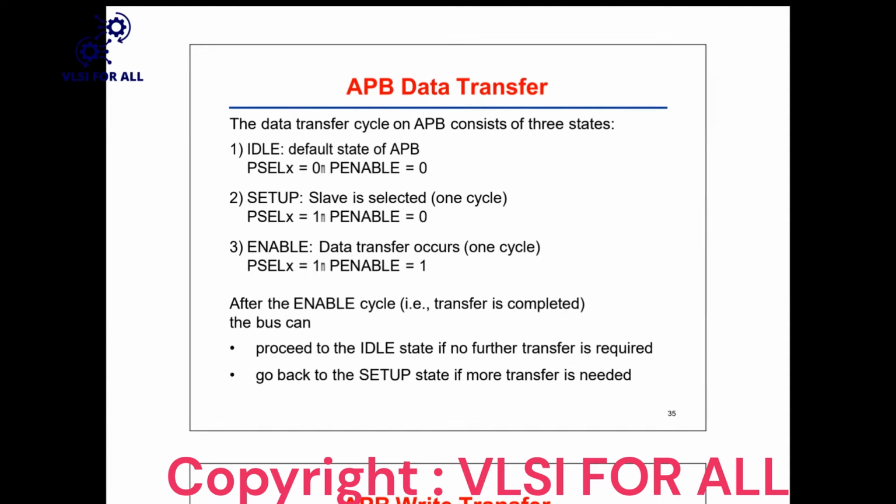But when a transaction has to be done, it has to come to the setup state. In the setup state, PSEL will be high, which means the slave has been selected, that is, the slave with which the master has to communicate. But data is not yet driven, because the slave is just selected from the master side, and whether that slave is ready to accept the transaction from the master is not yet confirmed.